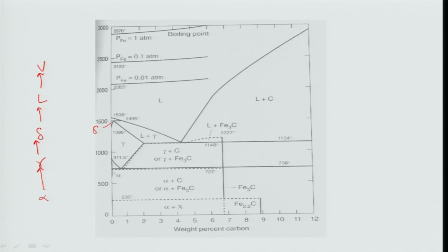And this temperature can vary as a function of the composition of iron. Therefore, this temperature is known as the A2 point. A2 is the magnetic to paramagnetic transition of alpha. So, I can write down for the alpha phase, A2 is basically alpha to alpha, this is ferro to paramagnetic. This is the A2 temperature point.